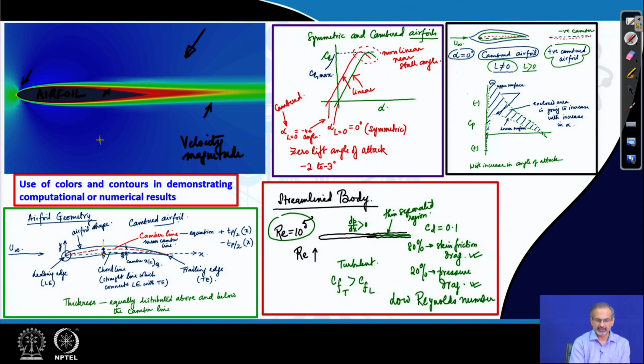So, you might imagine that the velocity vector at every point in the flow field, since this is a two dimensional one, will have a u and v component. So, what if you square and sum them up, and then what you have is essentially the magnitude of the velocity. So, the colors may be representative of the magnitude of the velocity, because then you do not need to make a separate plot for the u distribution and the v distribution. That would be the advantage.